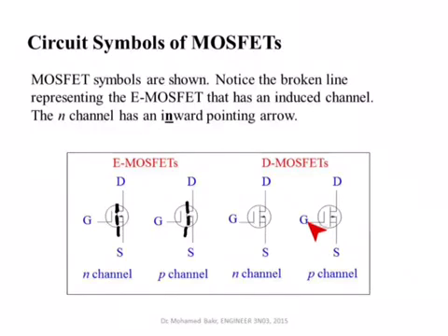This is the gate, it's of course connected to the electrode, and here we have the capacitor. This is the capacitor formed by the SiO2 layer of silicon dioxide, so this will act as the capacitor. And you have here the substrate is an N-type material. So we will focus in this course on N-type E-MOSFETs and the N-type D-MOSFETs. So conduction is happening through N-type material and a layer or a channel of electrons. Okay, but remember these 4 symbols and the meaning of these 4 symbols.